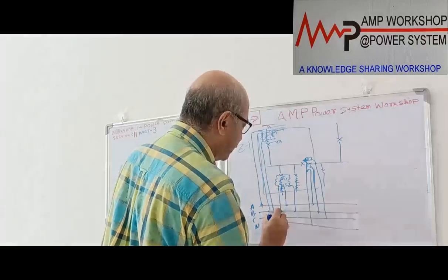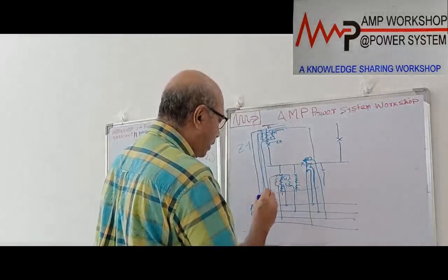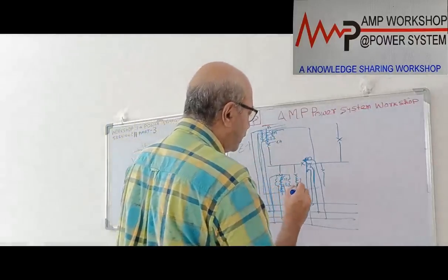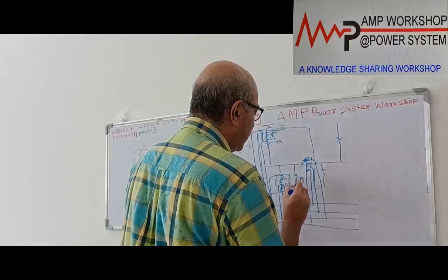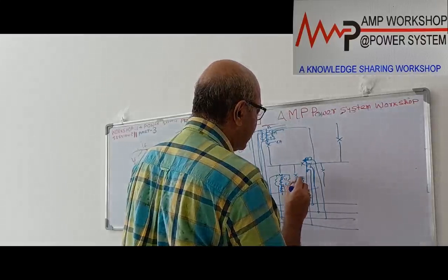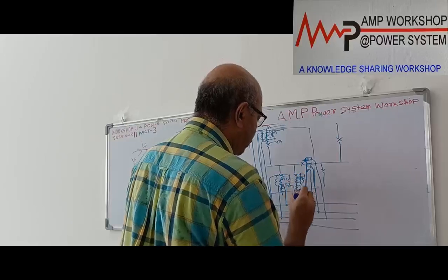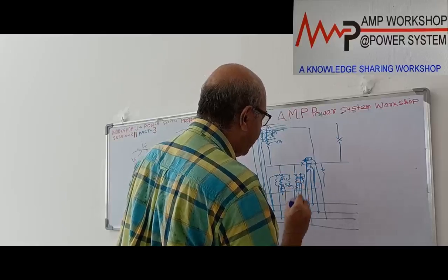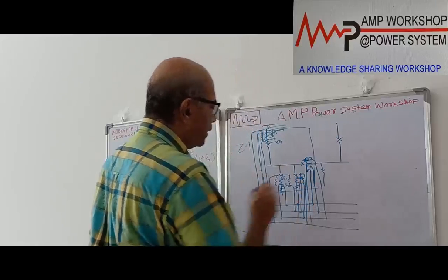This is B bus and this is C bus, right? And this neutral will be coming to the neutral bus. So you see all the outgoing, similarly these outgoing also connected this way. This is a 3 CT. These are shorted. It is coming to the neutral, and this CT will be coming. One is coming over here, second is coming B phase, and this is your C phase. So these are the CT connected.